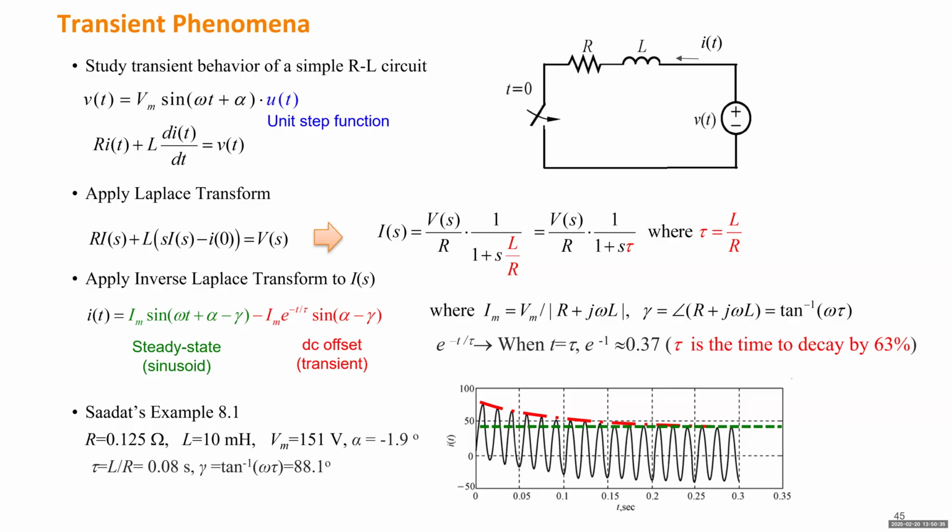In order to obtain the waveform of the detailed dynamic, you can definitely use the very accurate model, right, to integrate current and voltage, starting from the beginning of the disturbance. You're going to integrate many equations. For each generator, for a cylindrical rotor generator, you have 6 first order differential equations to integrate. And if you have many generators, you need to integrate many equations.